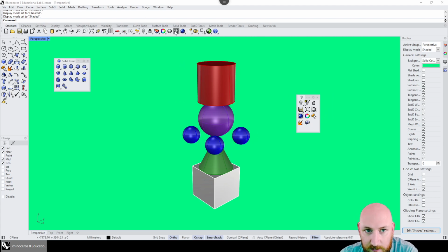And the other command I like to bring over is the isolate command. So that's in this light bulb one, which is sort of show and hide. And there it is, isolate objects. And hold Shift, move, hold Control, copy. So definitely hold Control and copy that over. And then you have it there. I'm going to delete it there because I already have it.